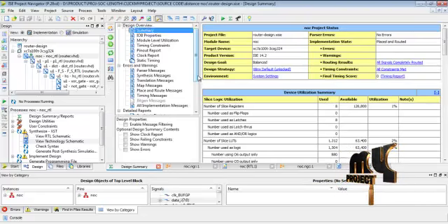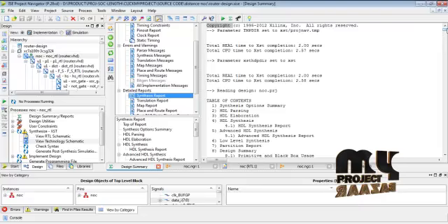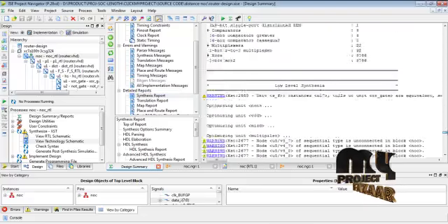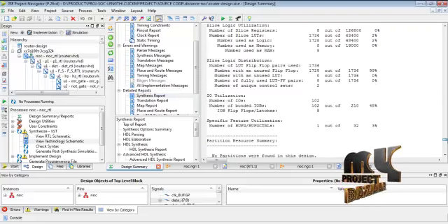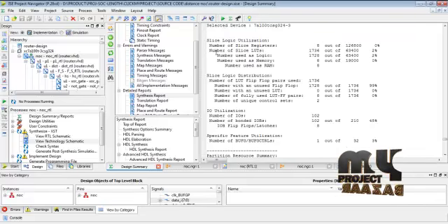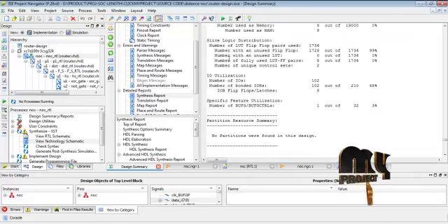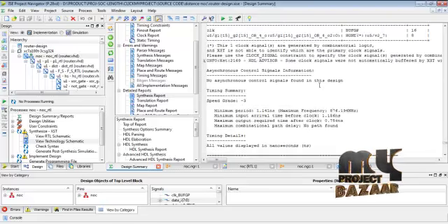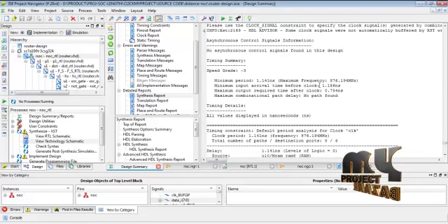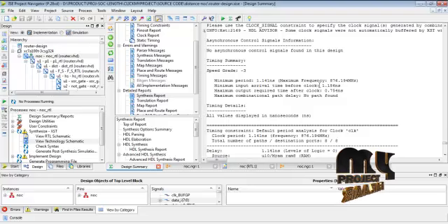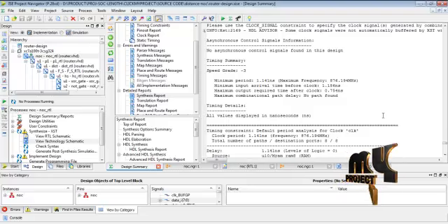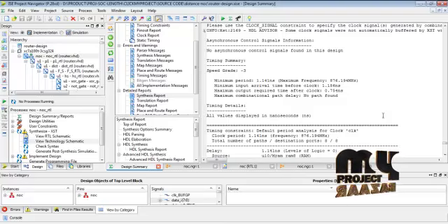Then we go to the design summary process, which generates the synthesis report with the device utilization result. This device utilization result identifies the area of the overall NoC architecture designs. Then the design summary process calculates the minimum period level and the clocking frequency. Then we calculate the latency level for processing time for the overall NoC architecture running process.